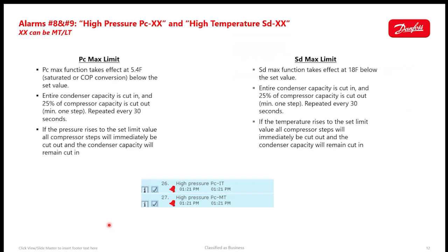If we go above 1500, then we won't continue with the staged approach. We'll say immediately that we're now in a safety concern with the relief, and we're immediately going to shut all the compressors off above that 1500 PSI limit. And so while we're in the range 1407 to 1500, it's staged. But as soon as we get outside of that range, it's either back to normal operation on the low side, or we're immediately shutting everything off on the high side above that 1500.